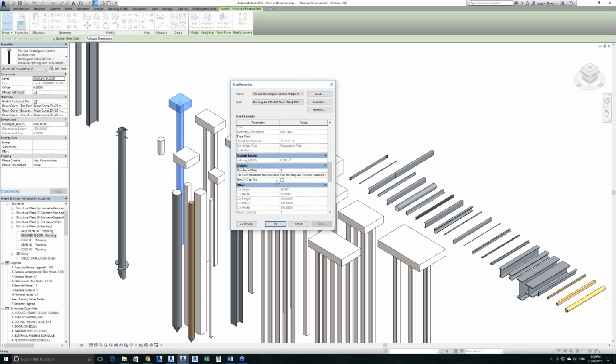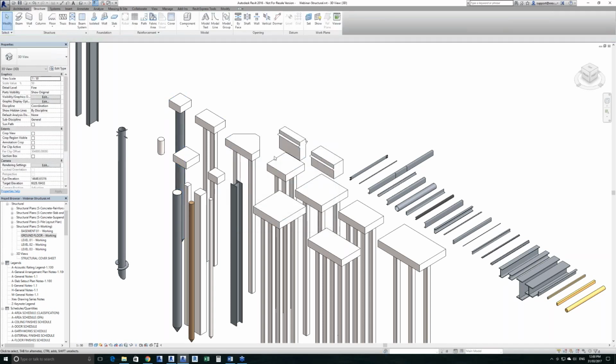Or, if that's not selected, it'll be calculated based on the pile spacing and clearance parameters, and there are tooltips built in as well. You can set what type of pile you want, maybe a steel pile on that one, and you can control the number of piles, and you'll see the layouts change as you specify different numbers, right up to 9, which is what we allow.